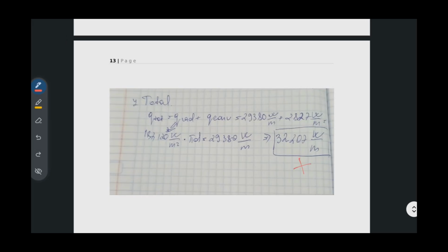So in general, we had 30 questions, and we discussed some questions from refining operations, especially from isomerization and DCU, delayed coking unit. And we discussed some distillation problems, especially from the operational challenges. One of them was the weeping, and the second one was the pressure drop in vacuum columns, and also the atmospheric distillation. And for the distillation column operations, we discussed also when you are increasing the reflux or decreasing the reflux, how your separation efficiency will change.